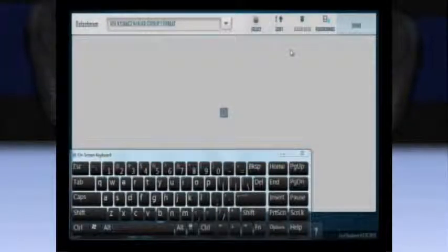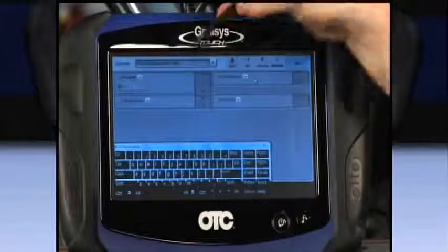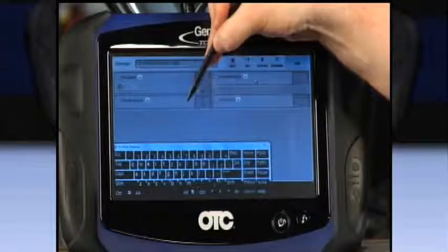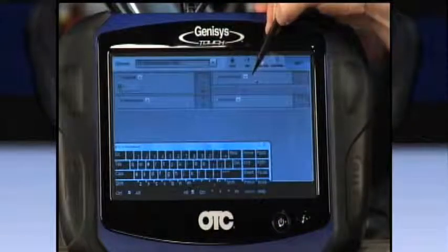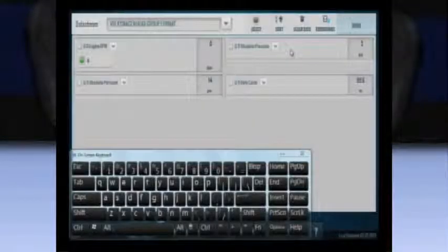And once again, it's going to interface with the vehicle, and I have my 4 fields again. In this particular case, I'm looking at engine RPM, boost pressure, the boost pressure that the computer wants to see or desired boost, and then duty cycle for the boost control valve or the N75 solenoid. Now, why is this important?